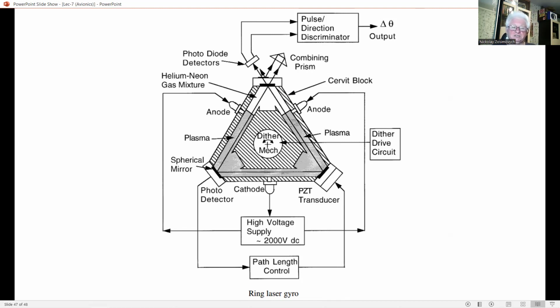Several manufacturers use quartz tuning fork rate gyros for deriving the aircraft attitude in their solid-state standby display instruments, a good testimony to their performance and attributes of small size, low power consumption, very high reliability, and competitive cost. It should be noted that the tuning fork gyro is not a new concept.